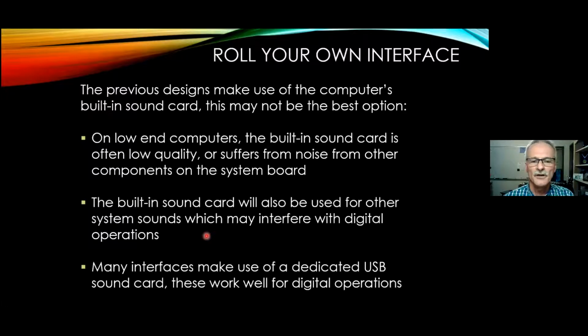So you have to be very careful, if you're going to use a built-in sound card, that you disable all system sounds from the operating system point of view, and also that you make sure you're not streaming any YouTube videos or anything like that, because you're going to be transmitting that sound out off of whatever frequency your radio is dialed up to. So a lot of our interfaces will make use of a dedicated sound card device, typically USB connected these days, because of course that's the connection of choice on all of our computers now.